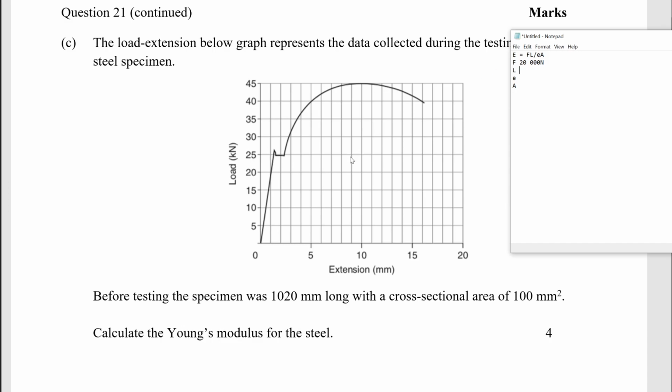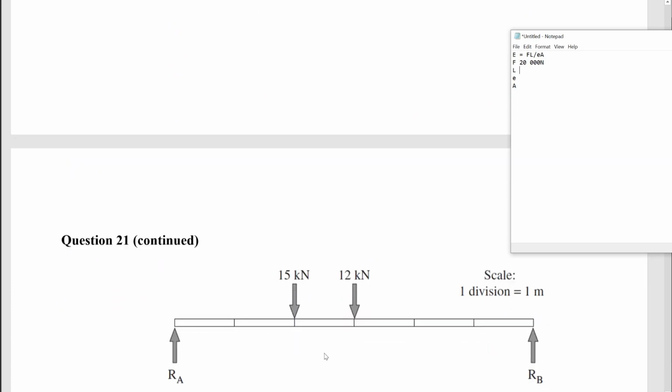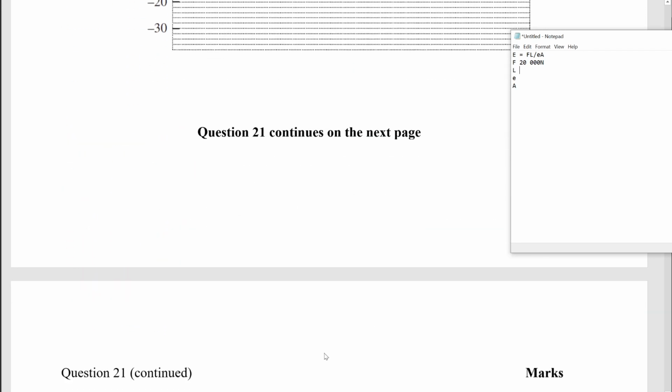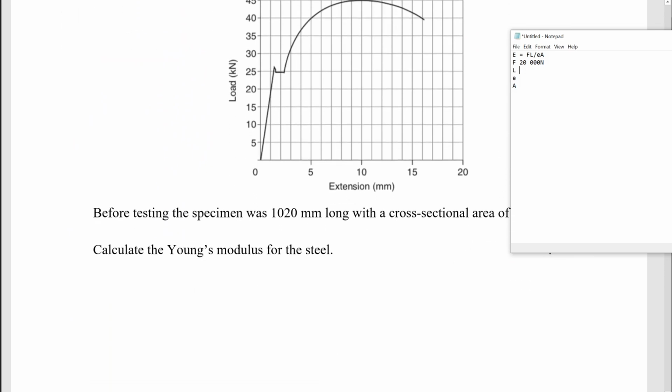When we're doing our bending, in this case here, we can give our answers in kilonewtons because we're not converting anything. But when we're converting things, we need to always work with newtons. And if we were to find the bending stress, we would at that point be converting, and we'd convert from kilonewtons into newtons.